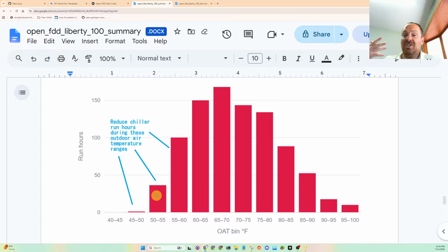You're having to condition that really cold or humid air. Then it's an energy penalty again. I feel like that involves a deeper dive that someone could validate first. A service technician goes on site, validates those dampers, actuation and good seals.